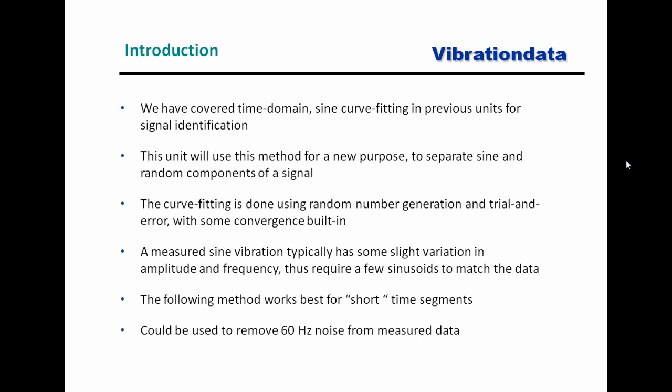Maybe this particular model, with different serial numbers of that model, will fly on a series of flights, but each will have a different trajectory. And the random vibration generated from the external flow may vary from flight to flight depending on the trajectory and the transonic and alpha Q conditions, and at what altitude those occur, and so on.